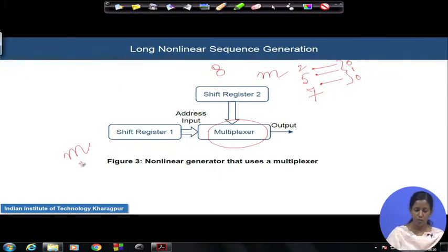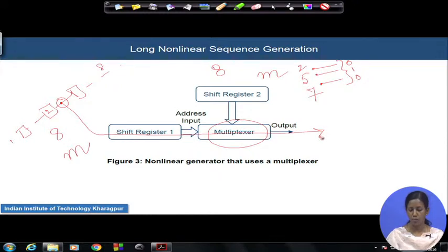In this shift register also there are 8 stages, going from 1 to 8. And this is 0, 1, 0, so the value of stage number 2 is being asked for. So, the step will be: whatever value is generated at the output of stage number 2 when the clock pulse came, it is connected directly to the multiplexer and comes out as an output.